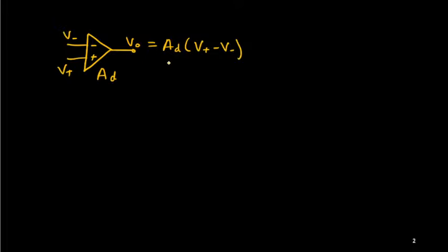This gain is very high, so it is generally not useful for normal operation in open loop condition, because quickly it will go to saturation level. If we want to use this op-amp as an amplifier, then we need to use negative feedback. This is important.